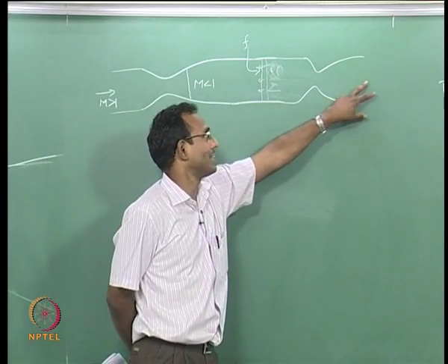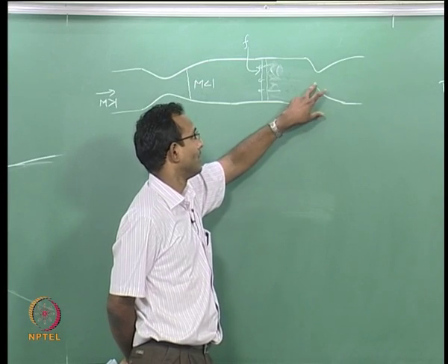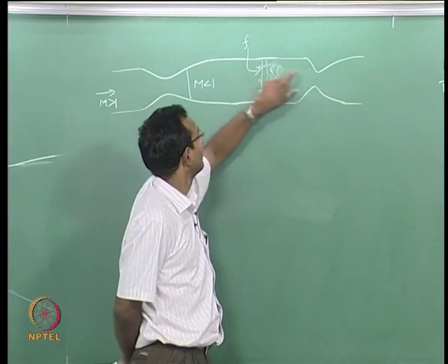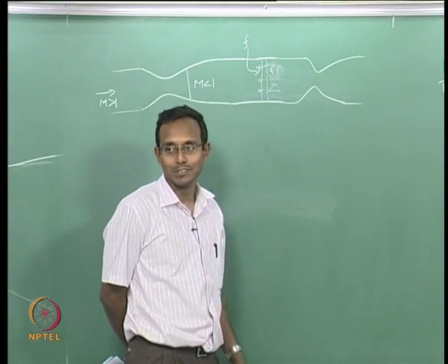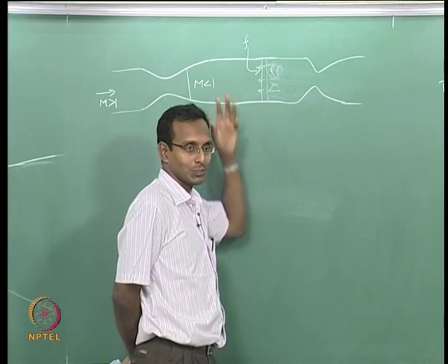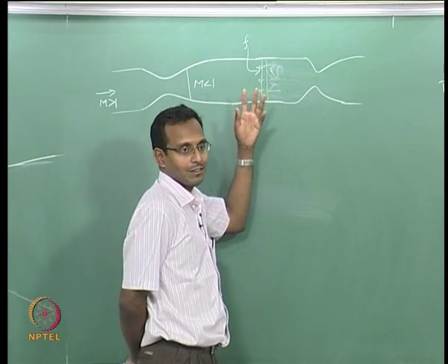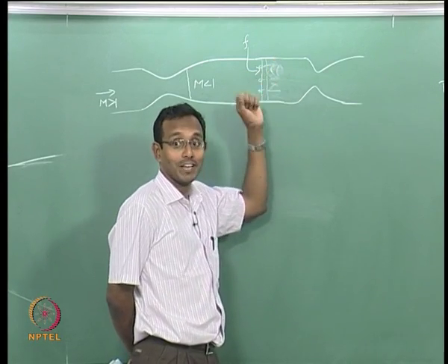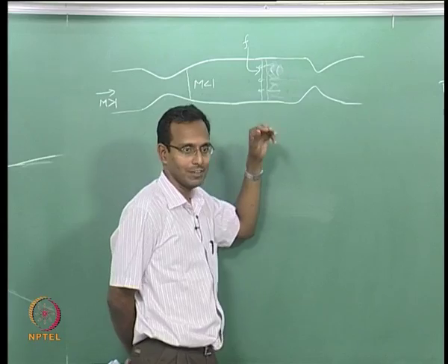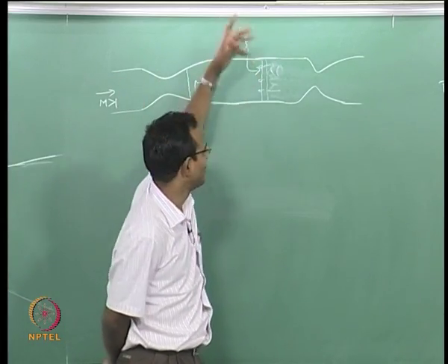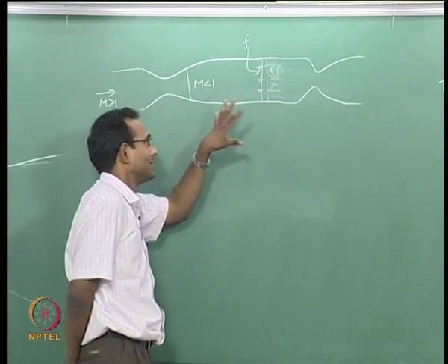So you have to think about it a little bit. It is going to be accelerated back, so here it will be typically choked. If it is choked here and I add a little more fuel to this, what happens? First thing, mass choking, or if I do not think about mass choking, there could be combustion, more heat release, thermal choking. Oh, in all this I did not talk about friction choking, that is also there. Every choking possibility is always happening there.